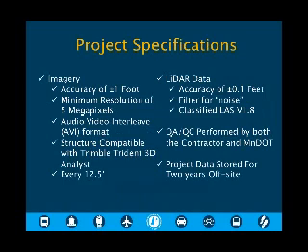Part of the reason why it took so long also, kind of what Trisha alluded to, was that this was our first real dive into mobile scanning and imagery. So we were trying to grab contracts wherever we could get them, to pull out some specifications and take a look at it. And we came up with the specs that you see there on your screen. And for the imagery, we wanted it within a foot, because that was good enough for where the guardrail was going to be extracted from that imagery. And if the guardrail is here or 1 foot over, that was close enough.